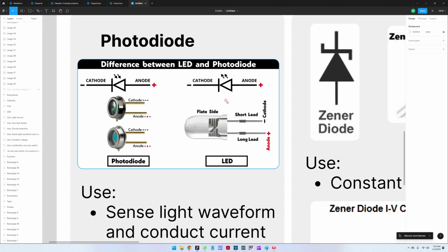So in the emitter from the TV, you have this diode here. This is emitting. You can see the arrows are going out, and this is emitting, for example, infrared signal. And then the photodiode on the TV, this translates this infrared to a different voltage drop on it, or it allows to pass a very small amount of current from the cathode to the anode.